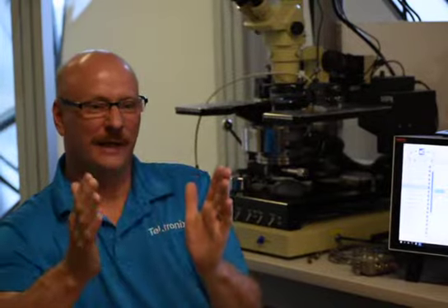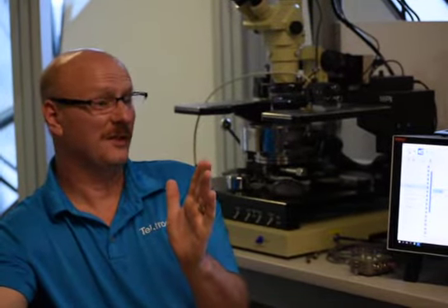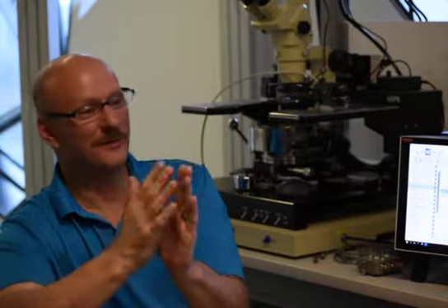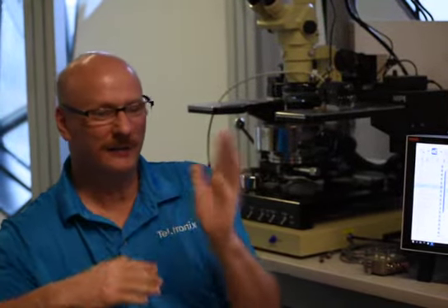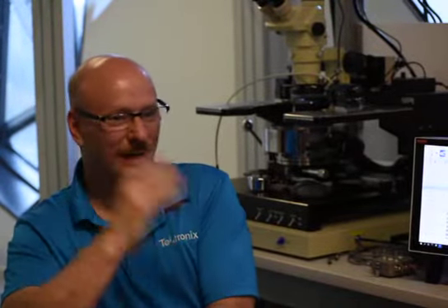Every SMU is in a slot, right? And the farther away the SMU is from the power supply, the more intense the calibration is, because there's capacitance of that backplane. So every instrument that's in this machine has to be calibrated in the slot that it's going to be in. You can't be calibrated outside the box. It's got to be calibrated in that slot, because if you move it over, now your calibration's off.